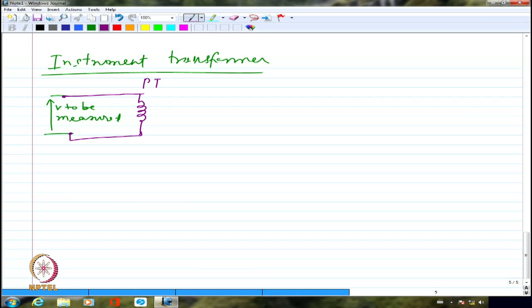So this potential transformer should essentially work similar to a voltmeter. A voltmeter generally offers a very large impedance. So similar should be the case as far as the potential transformer is concerned, because of which the secondary of the potential transformer will always be open circuited. It cannot ever be short circuited, or ever be connected with a tangible small value of resistance. No way. It should not be done. It should always be open circuited normally, and I may connect a voltmeter here. At this end, I may connect a voltmeter which will measure the RMS value.